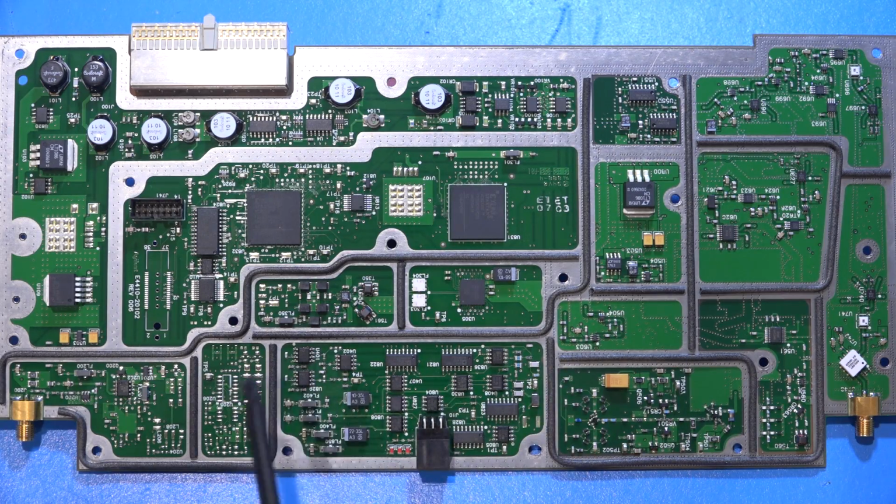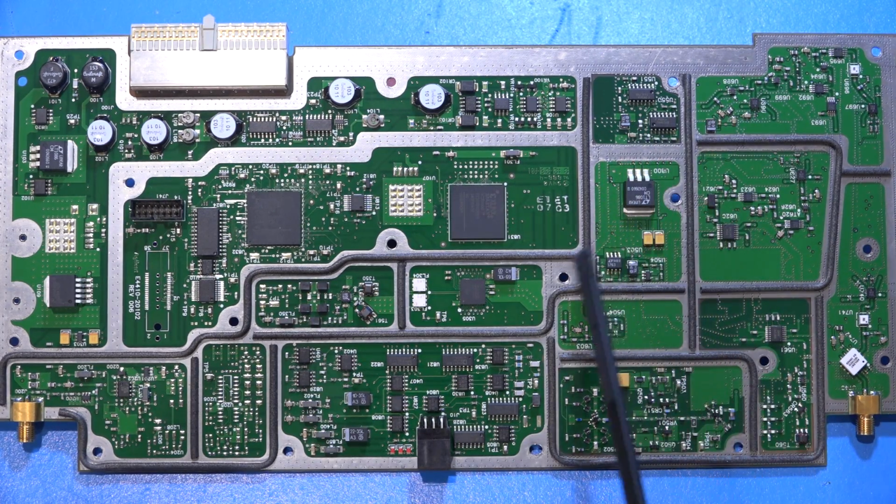The other place we can take a look is in order to make sure that this signal, which is coming all the way from here back, is present. We can scratch this trace here and attach an active probe to it, so we can monitor the signal going into the divider and see if the signal is strong and has the right frequency content, because there are so many doublers in the way, and if anything is dead, we wouldn't know. So I'm inclined to say that we should measure this guy and this guy as a starting point, and that should tell us a lot of information about how this works.